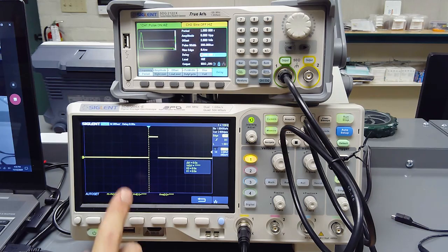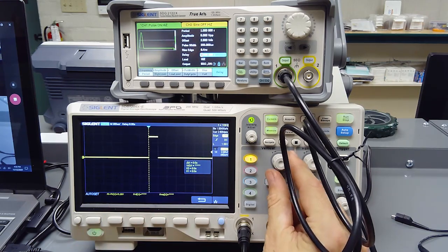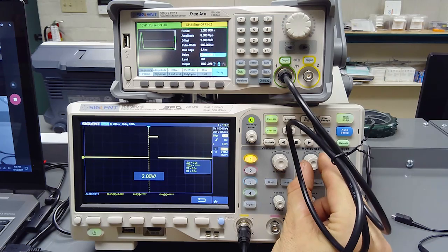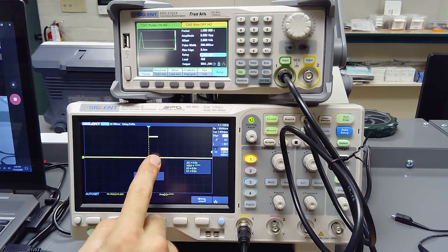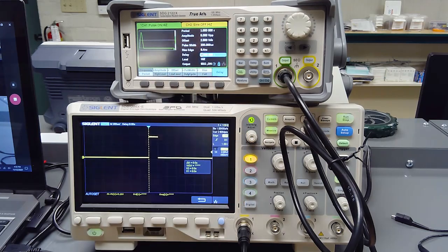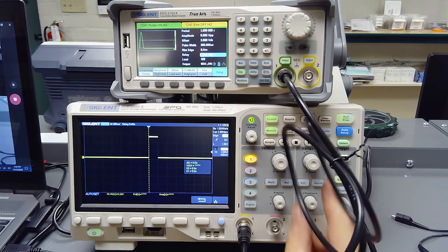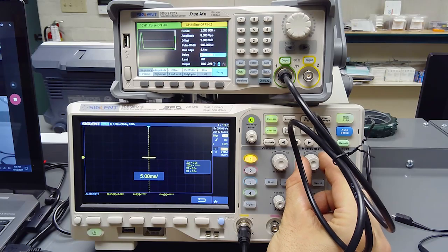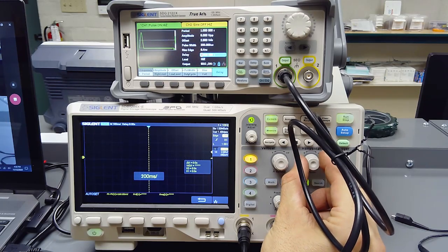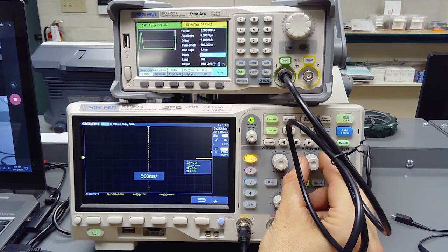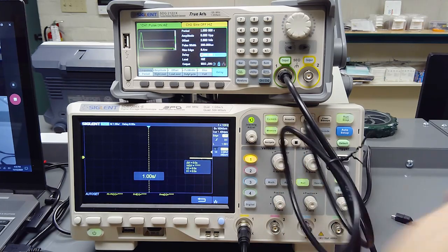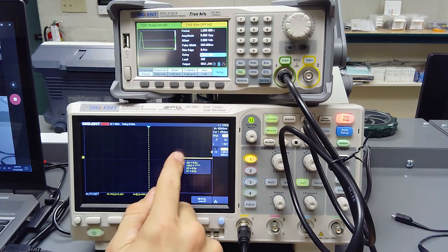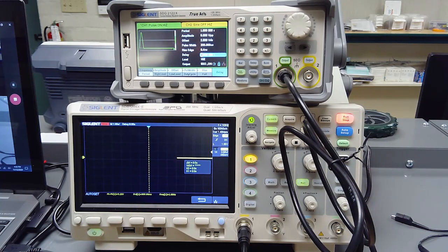It is one of these divisions, as you saw, was 200 microseconds. 200 microseconds. And if we look up here, the pulse width is 200 microseconds. And if I zoom way out, to 1 second per division, we can see each one of these ticks is 1 second apart. So that's how I would generate a short pulse, 200 microsecond pulse every 1 second that starts at 0 volts, goes to 5 volts, and back down to 0 volts.